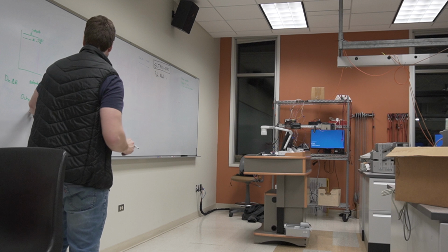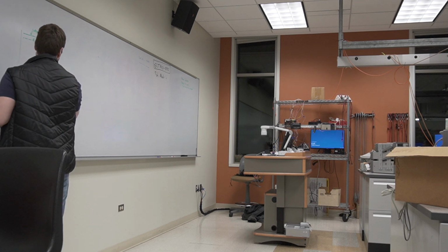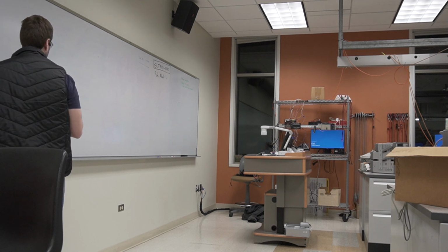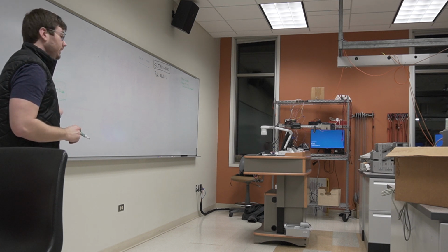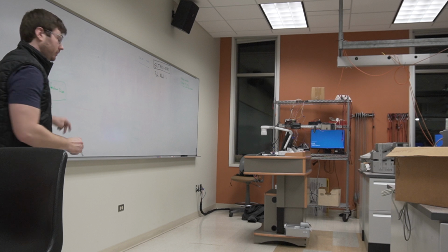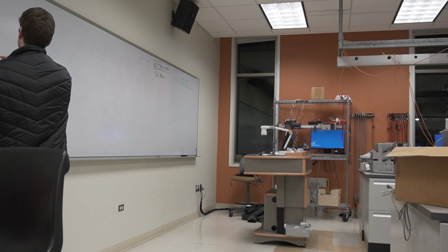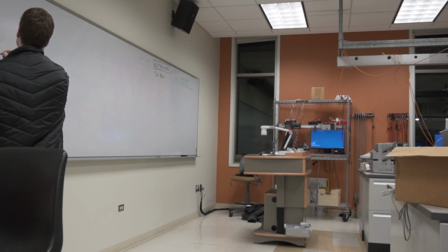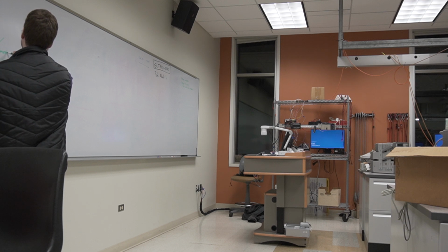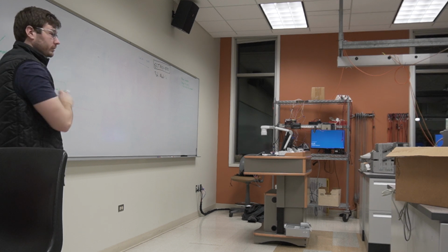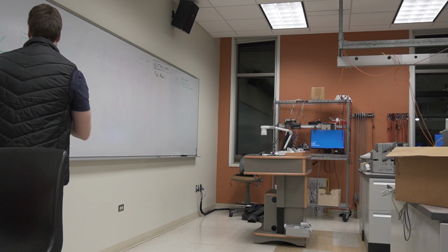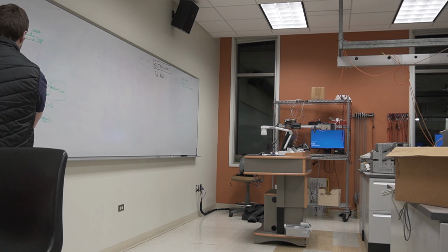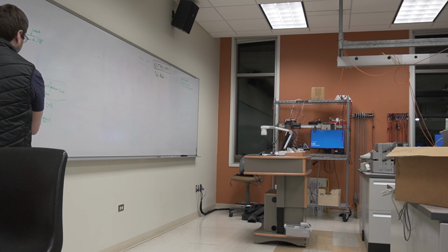This is what the math is literally doing if we ran it through a calculator for the PID algorithm. It's the proportional component, which is y = mx + b, our corrective slope. It's our integral component: how much error has accumulated over time, summing all of that up.